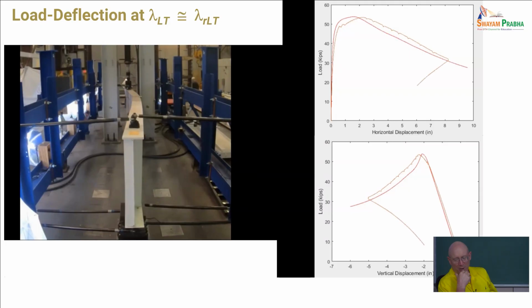And so we've got a behavior where there are initial residual stresses, then to that we're adding our major axis bending stresses, but with any out of straightness of the compression flange, as you're approaching the elastic buckling moment level for a member that has a slenderness close to lambda RLT, you're getting substantial lateral bending, and that's tending to cause a reduction.